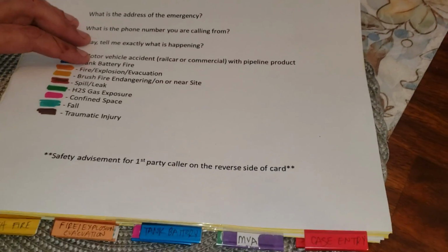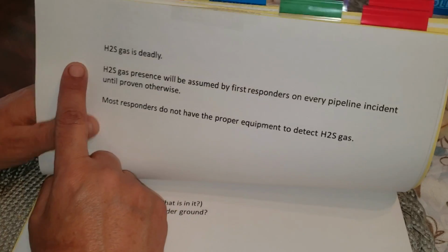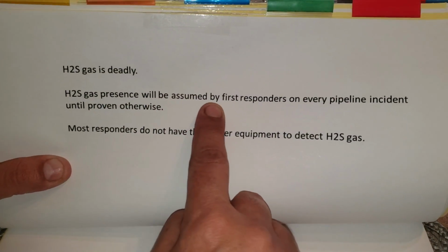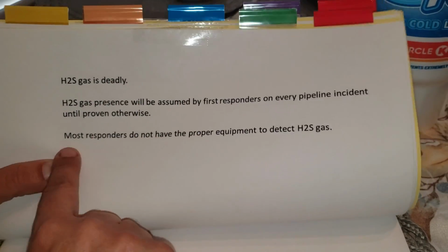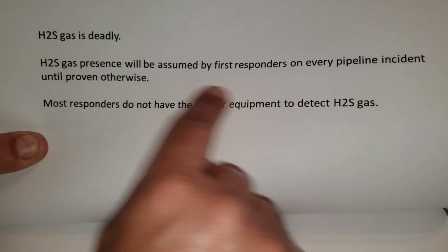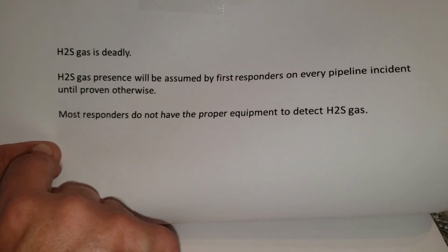So each one of these, like let's look at H2S gas. H2S gas. So it's pretty simple. How many patients have they been removed from the exposed area? Are they conscious? Are they breathing? A little bit about facts about H2S gas. It's deadly. The gas presence will always be assumed by first responders on every pipeline incident until proven otherwise. And like we talked about, most responders do not have the proper equipment to detect H2S gas. This is law enforcement, EMS, volunteer fire.